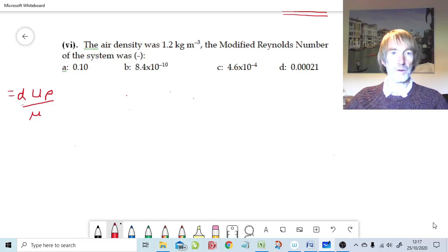Okay, so we get that from the volume of voids that's open to flow. So that's the length of the bed multiplied by the cross-sectional area times the voidage. So that is the meters cubed volume of voids in the bed. And then what about the solids? Let's take into account the presence of the solids.